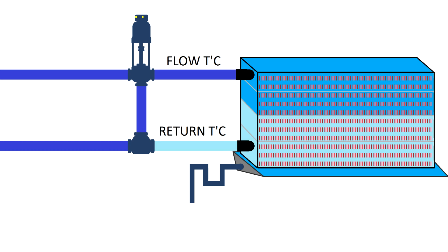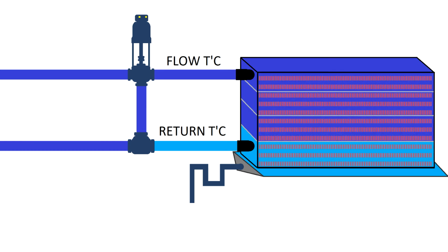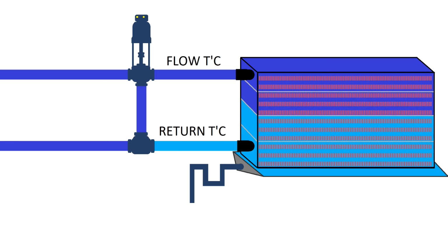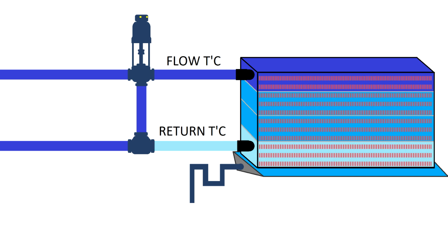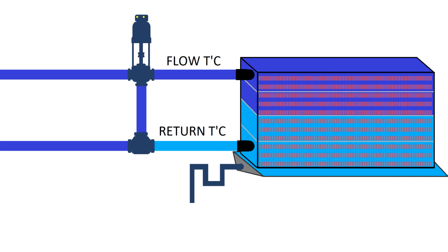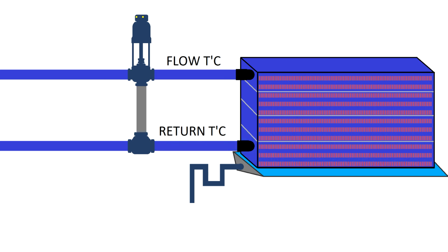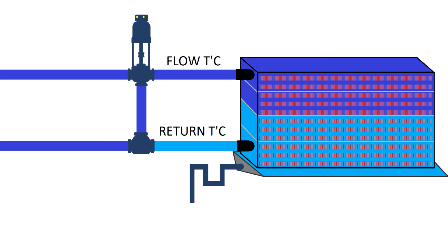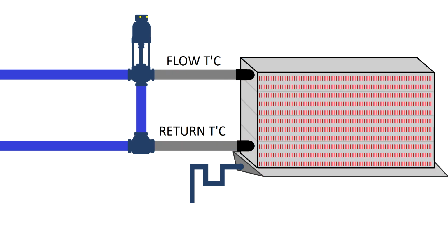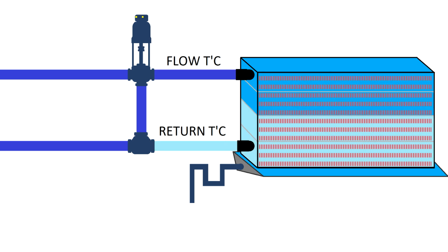So I had this problem before, and I measured the cooling agent on the flow. The return is irrelevant because you always have to have a delta T, and the difference between flow and return will be established by the designer. But if you want to have very good dehumidification capabilities, you have to make sure that when needed, the return will be above the dew point.